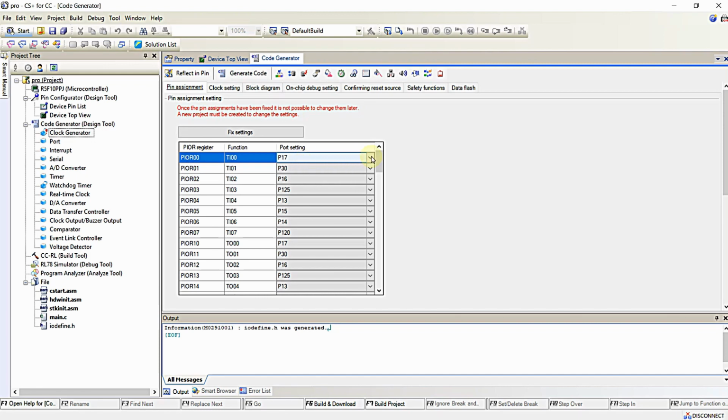Just click on this drop down. You can see the alternate pin that can be assigned with the same function is P66. If you want that particular pin to have this feature, you just select that. Most often we will not be changing anything right over here. We can use all these functions for all these pins as they are. If in case anything is required, I will intimate you in future lecture videos. But for now, we will be fixing these settings by default.